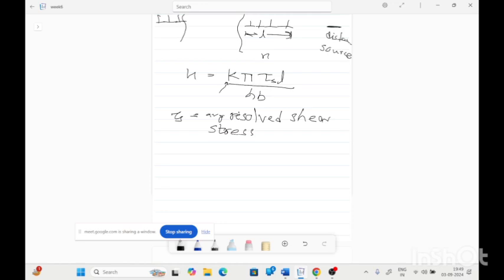So if the Burgers vector of a dislocation is b, the Burgers vector of a pileup of n dislocations will be n b, and the stress generated at the pileup can be written as n b tau_s.